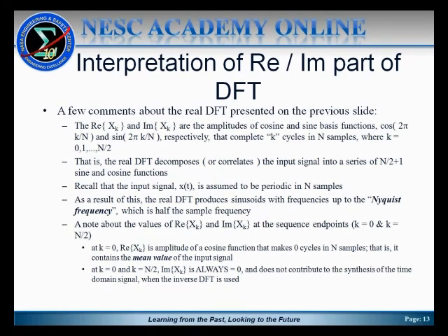That's very important. We'll show that with an example here, and then we'll talk again about it in part 2 when we discuss power spectral densities. If you have an input waveform with a constant bias, you will get a value in the discrete Fourier transform at a frequency of 0. So that's a key to you that you have a mean value in your signal when you see a value of the discrete Fourier transform or the power spectral density at a frequency of 0.